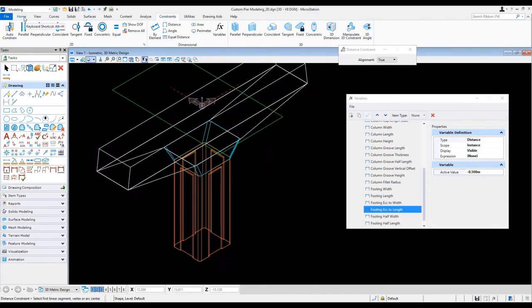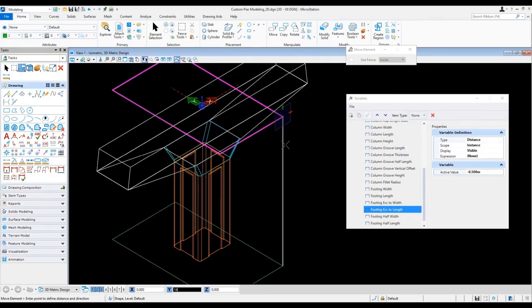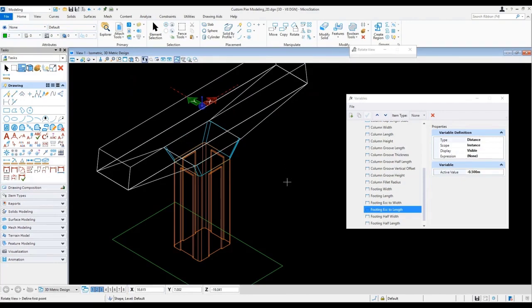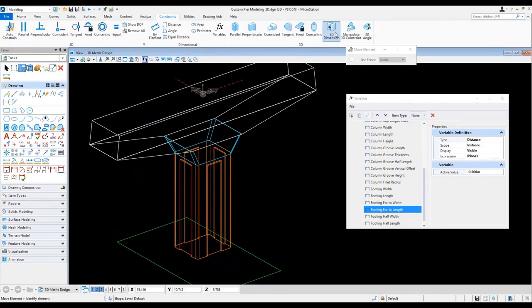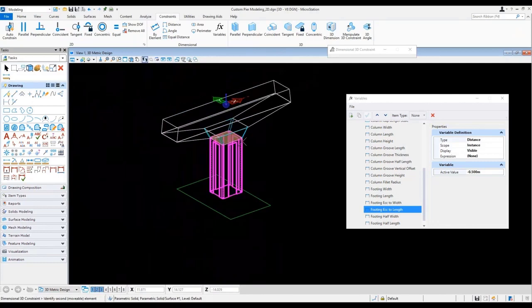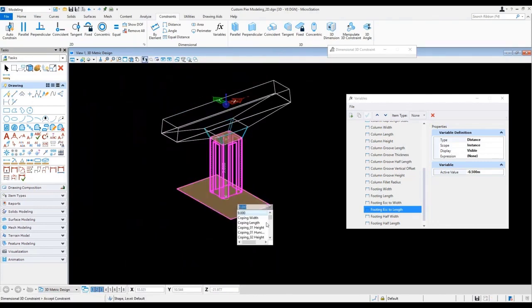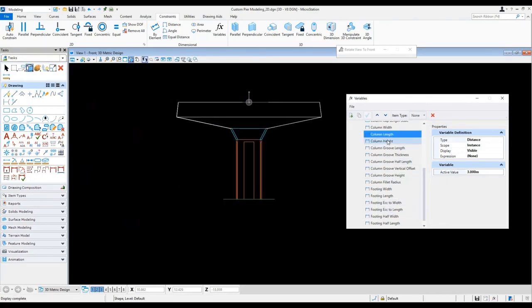Move footing profile to temporary location. But you should keep in mind the constraint has not to change during moving the profile. And connect the top of the column and footing profile using 3D dimensions. And confirm the footing movement due to column height.